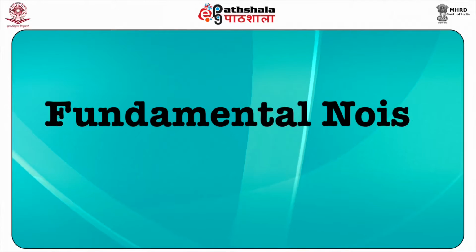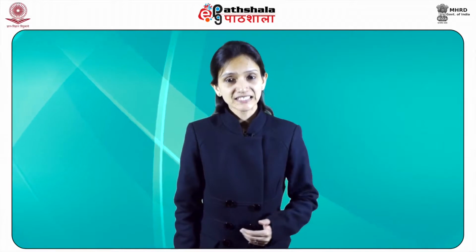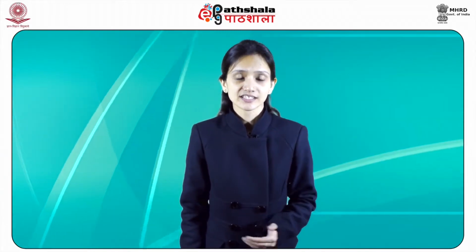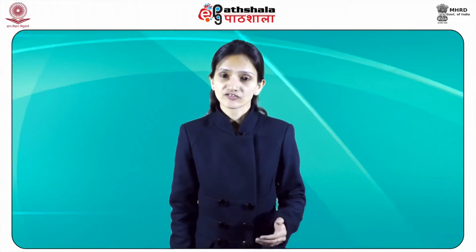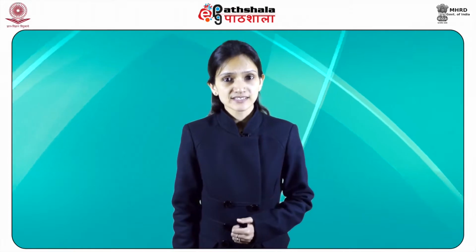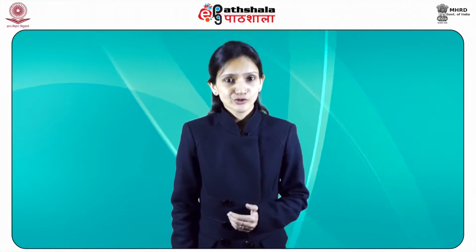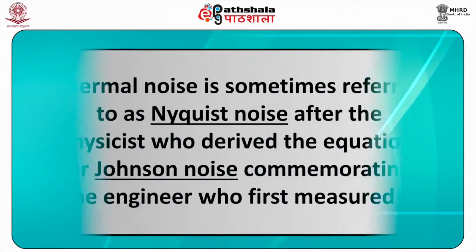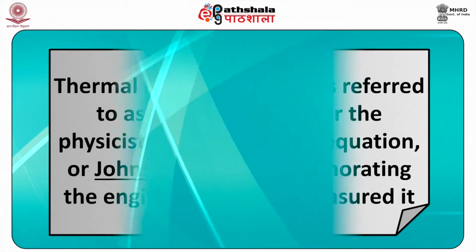First, fundamental noise. Thermal noise. Noise that originates from the thermally induced motions in charge carriers is known as thermal noise. It exists even in the absence of current flow. Since thermal noise is independent of the absolute values of frequencies, it is also known as white noise. Thermal noise is sometimes referred to as Nyquist noise after the physicist who derived the equation, or Johnson noise, commemorating the engineer who first measured it.